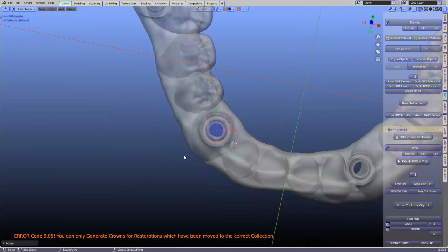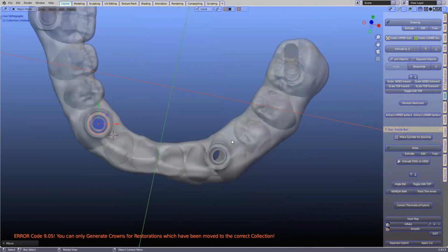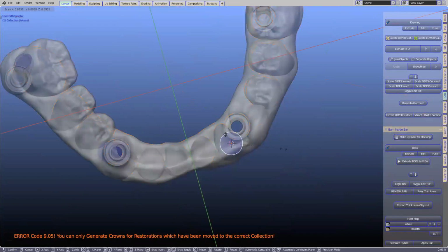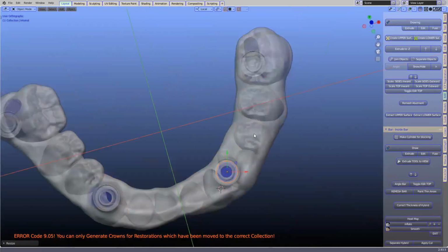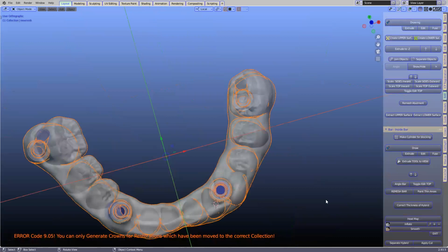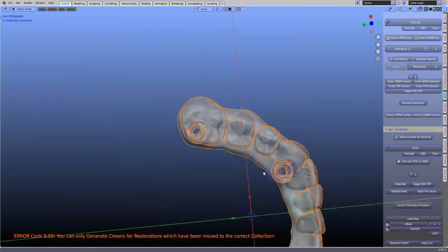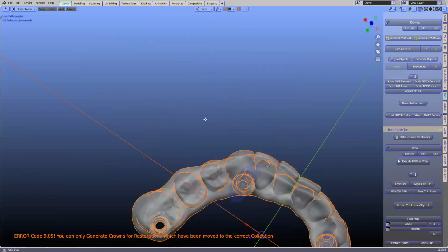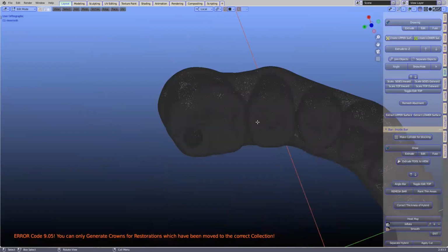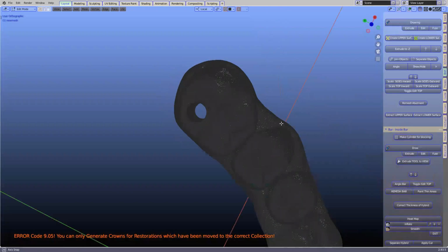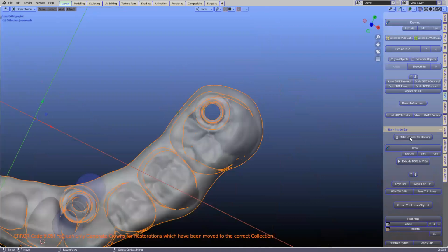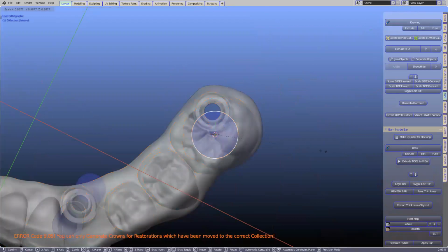So here's another one. Let's get that one done here, like that. Last one. It can be tricky to rotate. Sometimes what makes it easy is you go into edit mode, you grab a vertex like this, and then you rotate it, because it rotates around the selected object, which helps a lot. Oh, that's a good trick. Yeah.